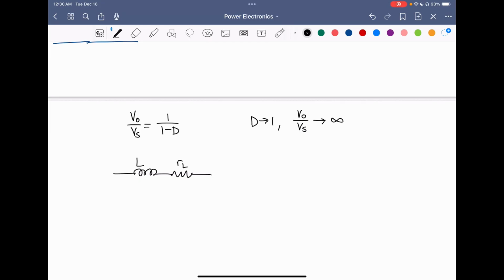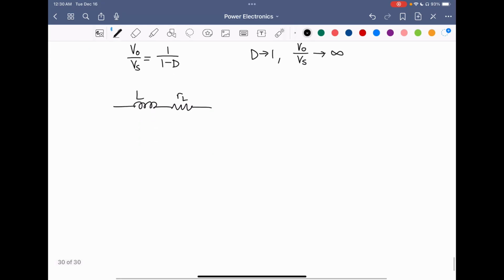In our analysis, we're going to assume that the inductor current is approximately constant. This is just to ease our analysis a bit. So we have the input power, the power that the source is delivering to the circuit, PS, equal to the output power. However, we also have some power loss in the resistor, so that equals the power loss due to the series resistance.